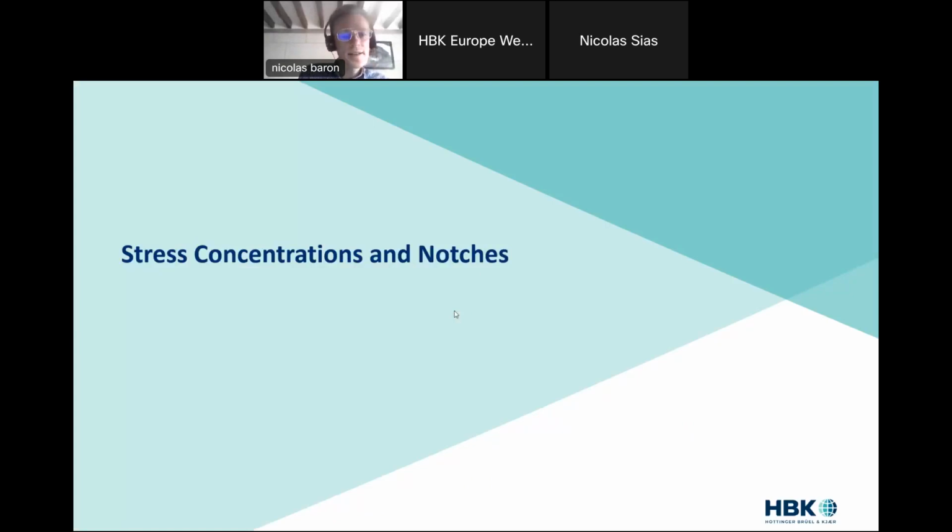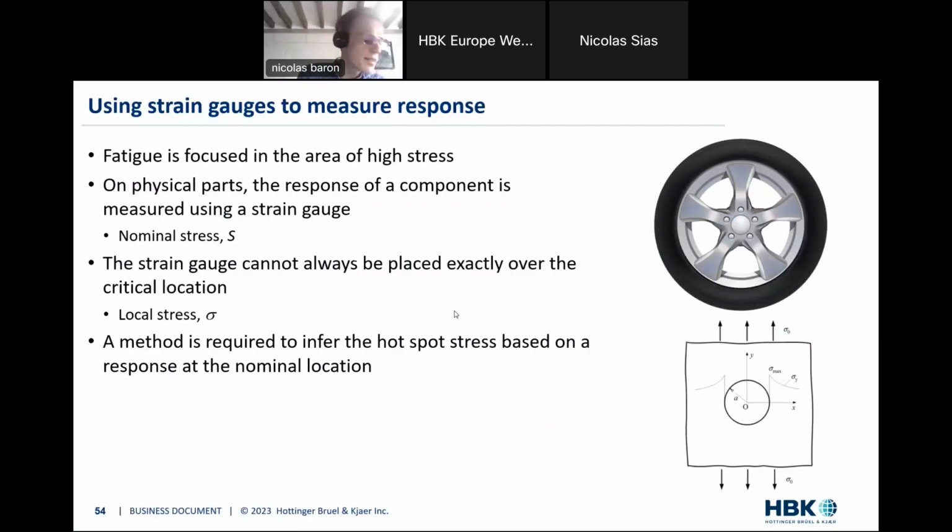Okay, stress concentrations and notches. Remember when I talked about the Havilland program, the English program in the 50s, where the airplanes just crashed, and that was the end of the program. I mentioned the word stress concentrations, and that was one of the reasons for the fuselage to break down. So stress concentrations and notches are responsible for many or most of the fatigue failures. We have to address them appropriately. So let's look at this now.